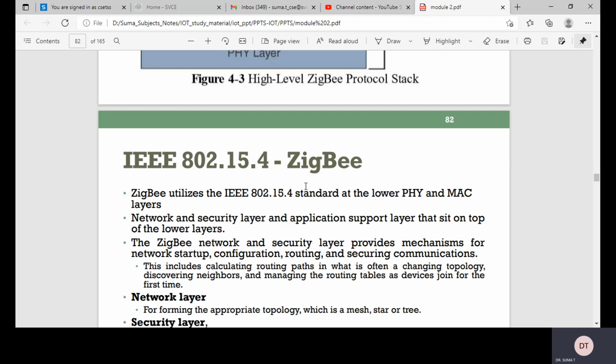These sets of commands and message types are called clusters. Ultimately, these clusters from different functional domains or libraries form the building blocks of ZigBee application profiles. So vendors implementing predefined ZigBee application profiles like home automation and smart energy can ensure interoperability between their products.